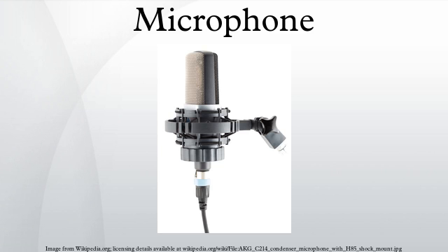Liquid microphone. Early microphones did not produce intelligible speech, until Alexander Graham Bell made improvements including a variable resistance microphone transmitter. Bell's liquid transmitter consisted of a metal cup filled with water with a small amount of sulfuric acid added. A sound wave caused the diaphragm to move, forcing a needle to move up and down in the water. The electrical resistance between the wire and the cup was then inversely proportional to the size of the water meniscus around the submerged needle. Elisha Gray filed a caveat for a version using a brass rod instead of the needle.